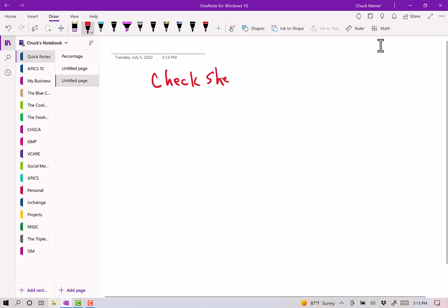What a check sheet is, as I mentioned, a way to collect data. And the most common way that you'll probably see this is you'll have an issue on the factory floor with a dimension or a measurement or a characteristic, and it could be an existing part or a new part. Call up the engineer. The engineer looks at it, works with it, and then turns around and says, not 100% sure what's going on, but let's collect some data. And so they'll say, hey, for the next couple of days as you're making it, will you keep track of what happens for issues and how often?